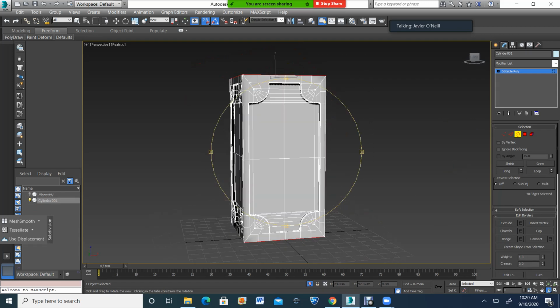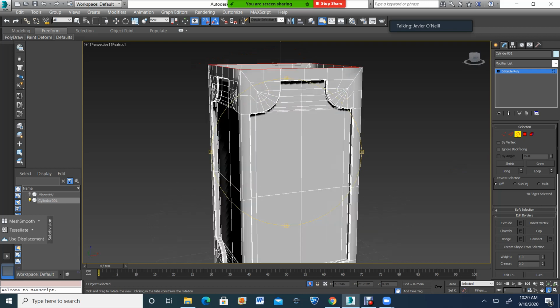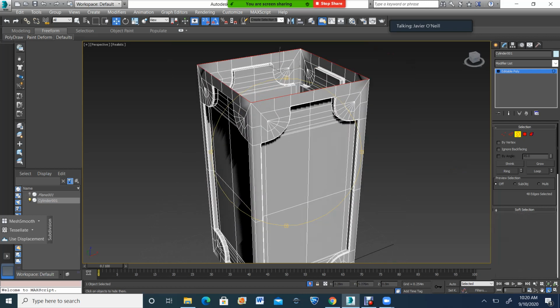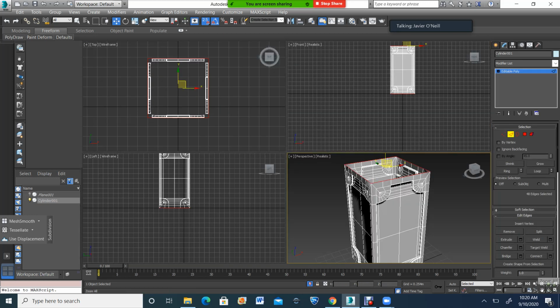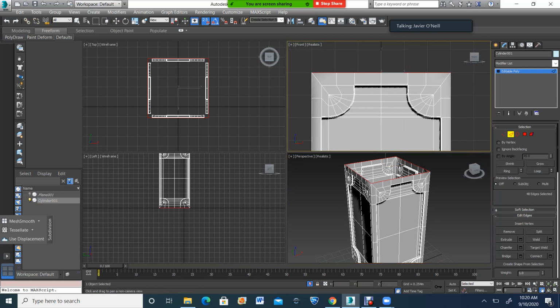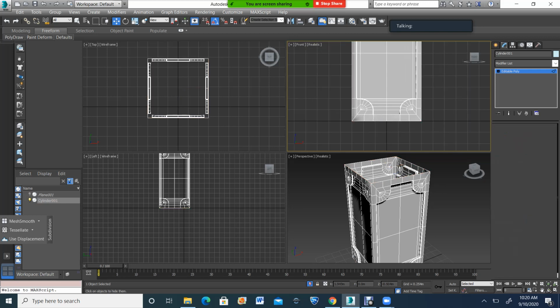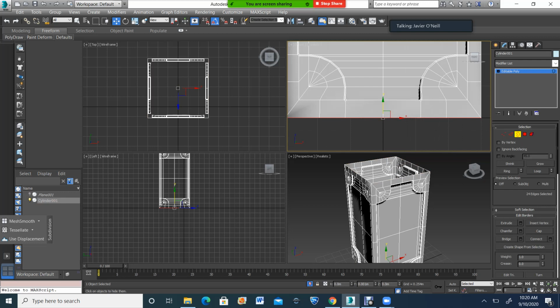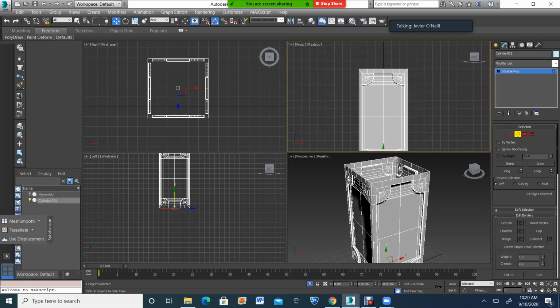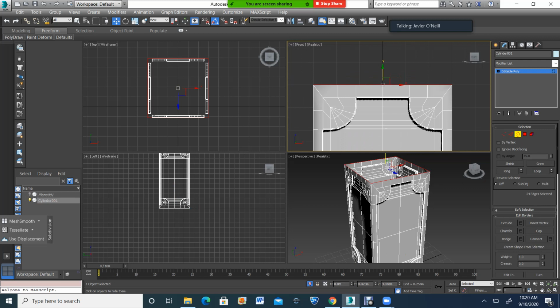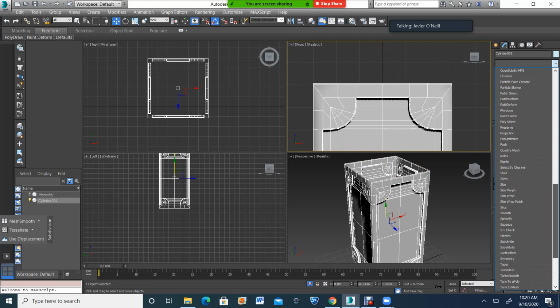That's good. So what we are going to do now, just to help preserve these two shapes, for example, is we're going to go ahead and make an extrusion upwards here. So you can have that cut so it preserves that nice squarey little shape. So I will press S to turn off my snap so it doesn't go to a crazy place. Extrude it slightly upwards. See, and I didn't want to do that. I got both borders selected, so this time I'll select just one. Extrude outwards. And then select the top one. Hold Shift, extrude outwards. Control Save as always, because this program is unstable as fuck.